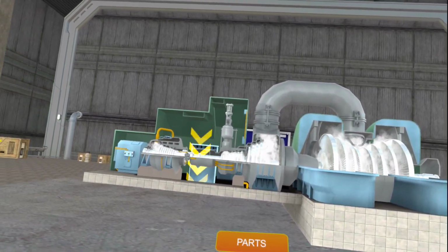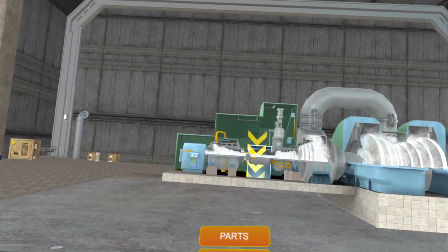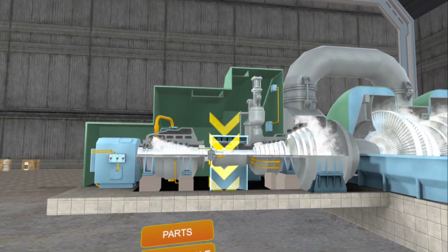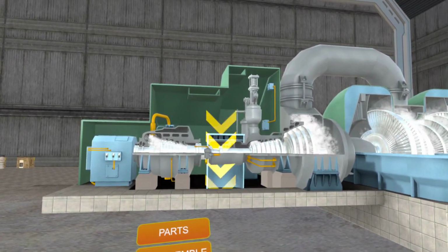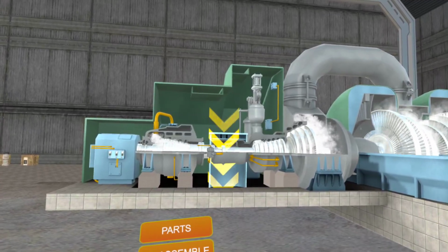The thrust bearing absorbs the residual thrust produced due to the steam flow in the turbine steam path. The thrust bearing serves to maintain the axial clearances in the steam path, and the same is monitored by axial shift probes, which give alarm and trip values.